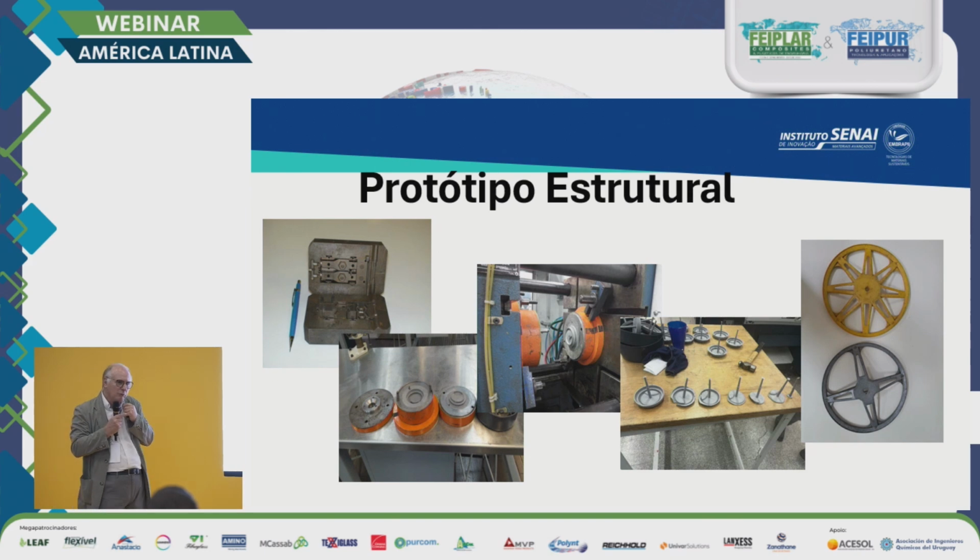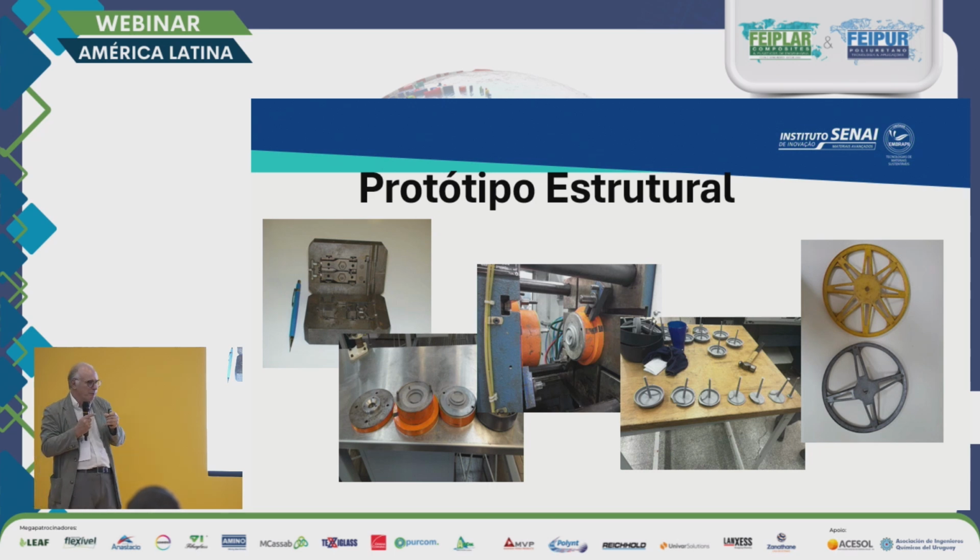When we think about replacing a metal by a polymeric material, you have to think about the differences in property. There are huge differences in property. One is more flexible, the other one is more rigid. So what's the point? You have to think about changing the geometry to be more robust, bigger, with more notches. So the pieces will define the conditions.